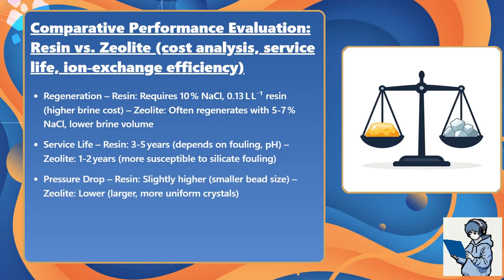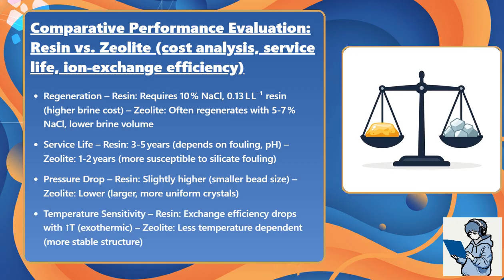Pressure drop: resin slightly higher, smaller bead size. Zeolite lower, larger and more uniform crystals. Temperature sensitivity: resin exchange efficiency drops with temperature increase. Zeolite is less temperature dependent, more stable structure.